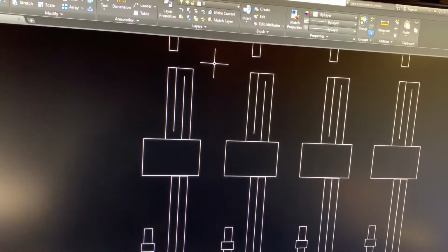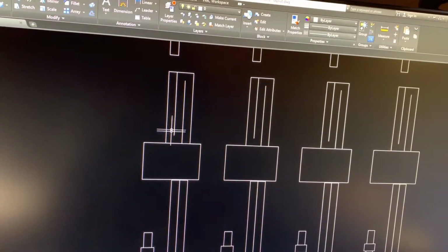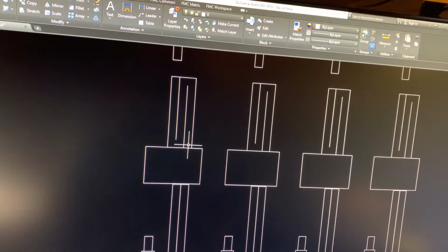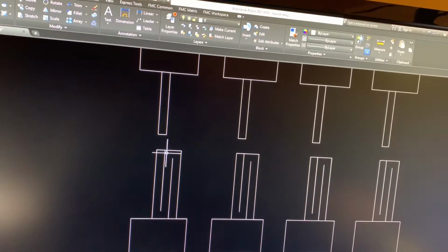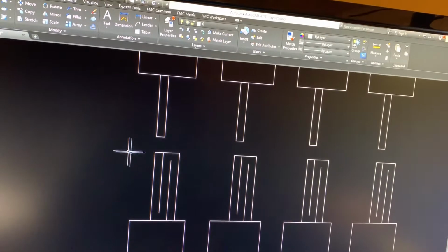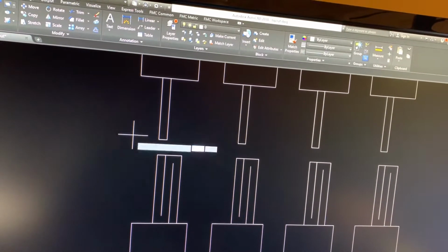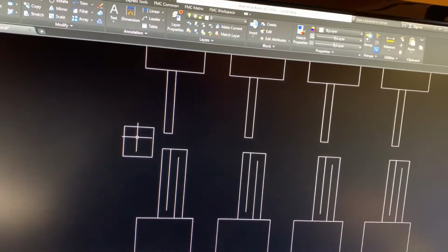Okay. Then over here, they'll be pushed out and they'll go along here and they'll be sitting here for a while until they're cool. So after they're cool, there'll be an operator here who will knock out the metal out of the sand casting and put all the sand into a bin over here. Sorry, I don't have the bin drawn. Here you go. Okay, put it into the bin here.